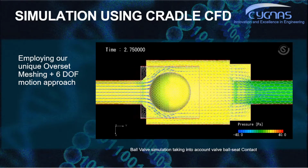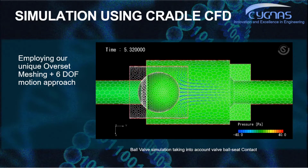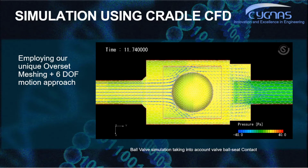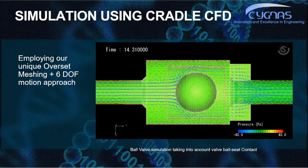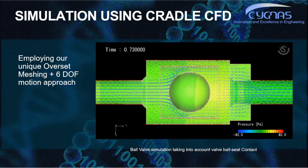The ability to handle the valve ball seat contact is important here because it enables the ability to simulate the stages of opening and closure. During these stages, we sometimes observe a vibration of the ball, which can cause some mass flow or pressure fluctuation at the exit, which most of the time are completely unwanted.